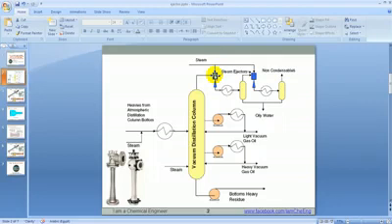Hence we are going to reduce the boiling point even more, as we discussed, that by decreasing pressure, we are increasing our ability to obtain lighter fractions of oil by reducing the boiling point of the mixture.